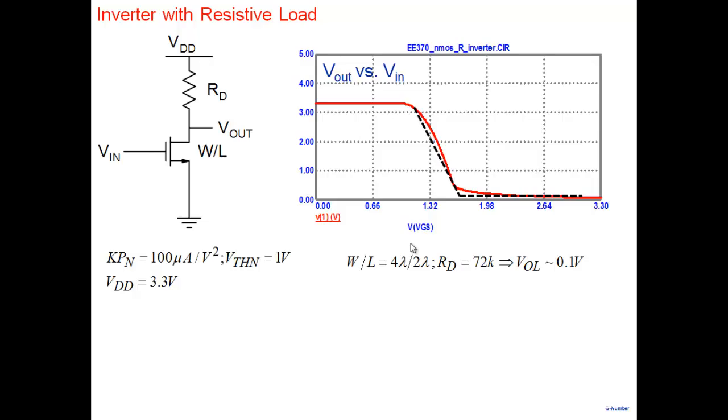So the first one I'll leave the detailed calculation for you to do in the homework. What I'm saying is, note that what is really happening is the region is zero gain because the transistor is off. Then the transistor turns on. Once the transistor turns on, which state is the transistor in? Just when the transistor turns on. We looked at that question earlier also. So you have applied a voltage a little bit larger than the threshold. The transistor is turning on, and the output is what? Still close to VDD. And note that the transistor is in saturation region.